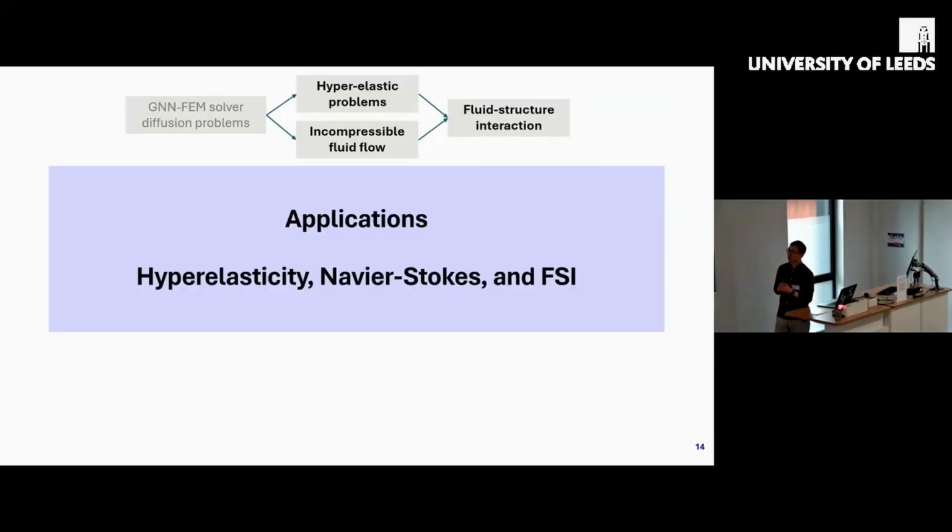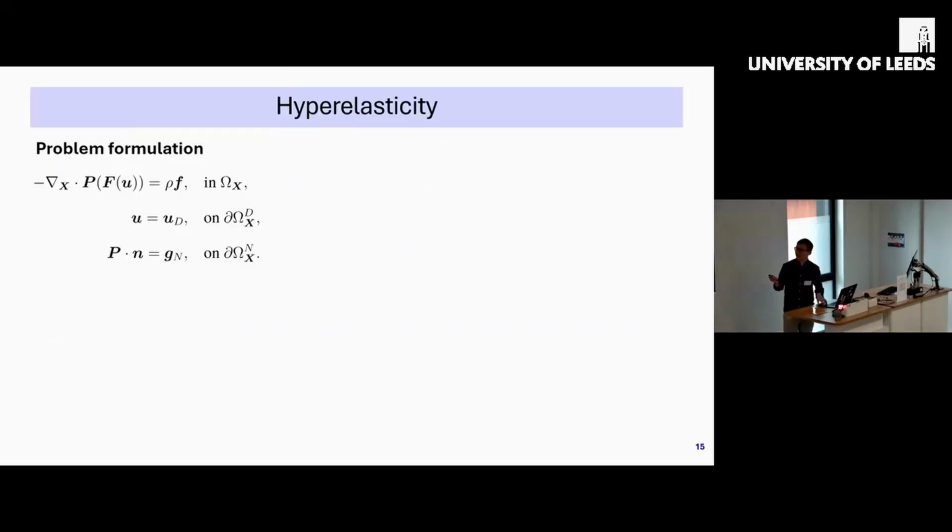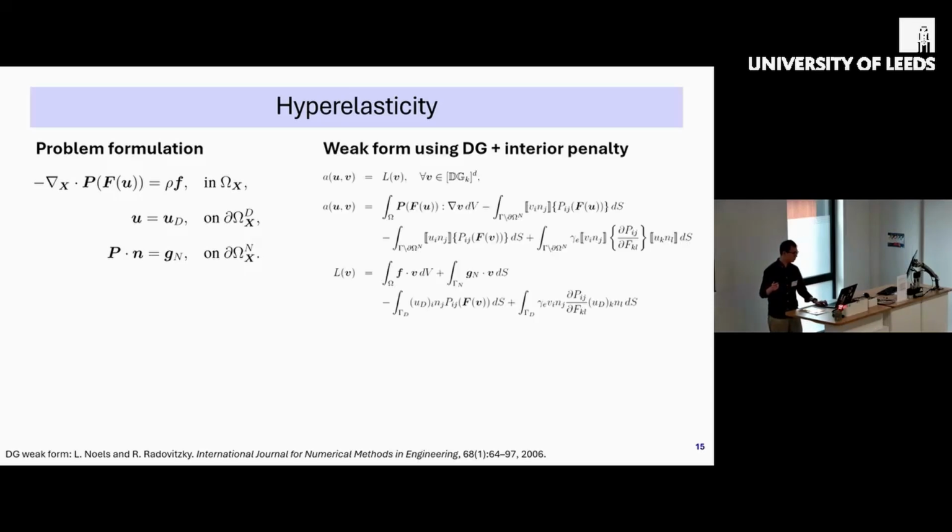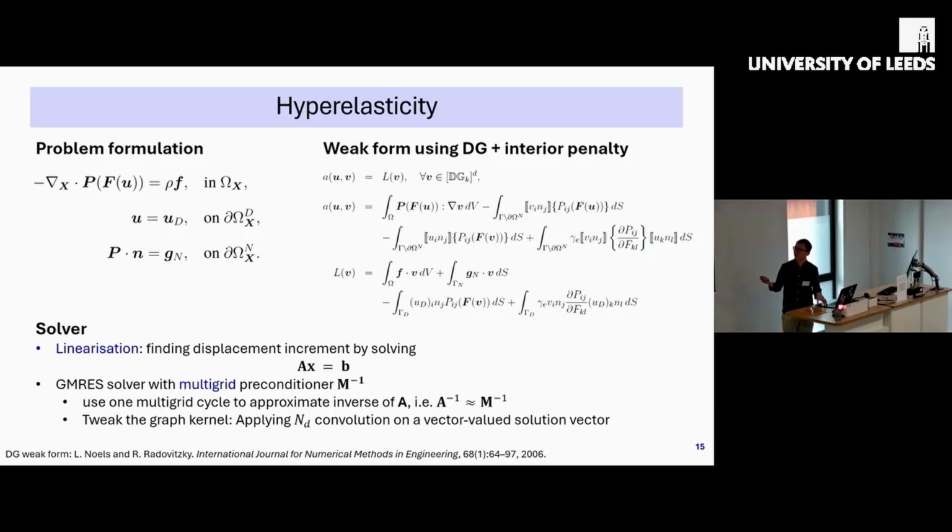Next, I'm going to introduce how this is applied to hyperelasticity, Navier-Stokes, and fluid structure interaction. For hyperelasticity, it has a governing equation very similar to the diffusion equation we saw before, and even the weak form is very similar. The difference is that it's a nonlinear equation, so you have to do some linearization. I'm using Newton linearization here. So at each Newton step, you are solving for the displacement increment by solving this equation here.